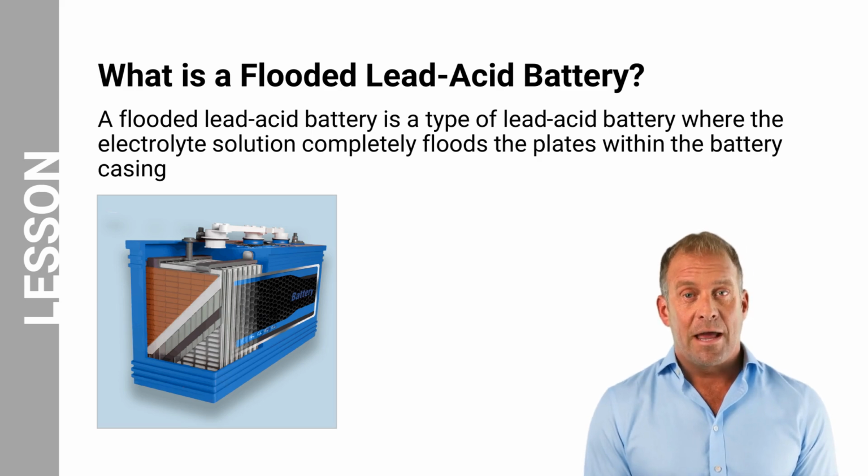What is a flooded lead-acid battery? A flooded lead-acid battery is a specific type of lead-acid battery in which the electrolyte solution completely floods the plates within the casing. These batteries require periodic maintenance, such as topping up the water content in the electrolyte as it evaporates over time. On the other hand, a lead-acid battery is a broad category encompassing all batteries that utilize lead plates and sulfuric acid electrolytes for operation. They are a mature and well-established battery technology.